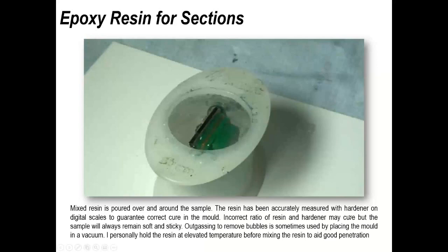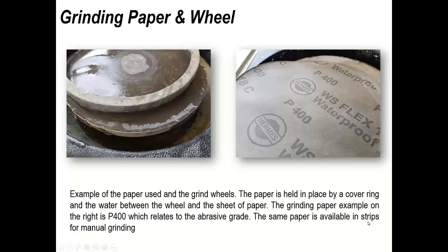So again, we put the epoxy in there. We're going to leave it in an oven an hour, 2 hours, and then that sample will be fully cured, and I'll be able to move on to the next stage. So with microsectioning, the next step is you can either do it manually, as I was trained, which I wouldn't recommend, it's extremely boring, or you're using rotary tables. The rotary tables I'm showing here on the left-hand side are basically a table that's rotating. You're dribbling water onto the surface to wash away the residue and also keep the temperature low.